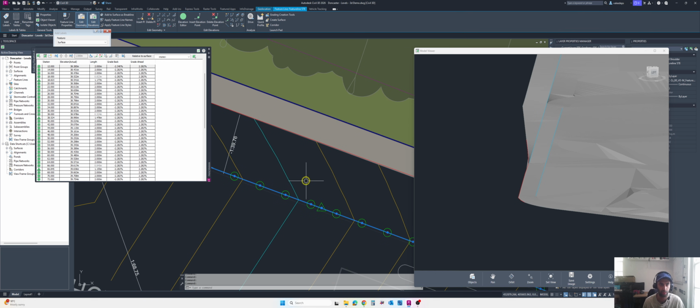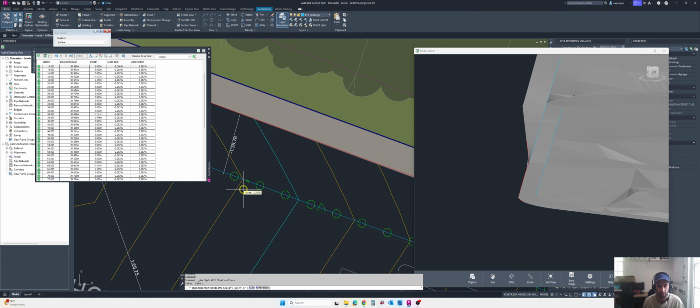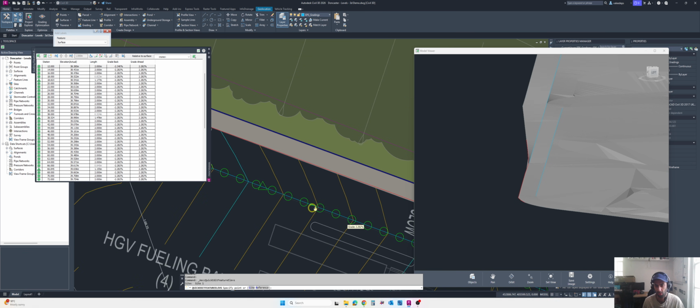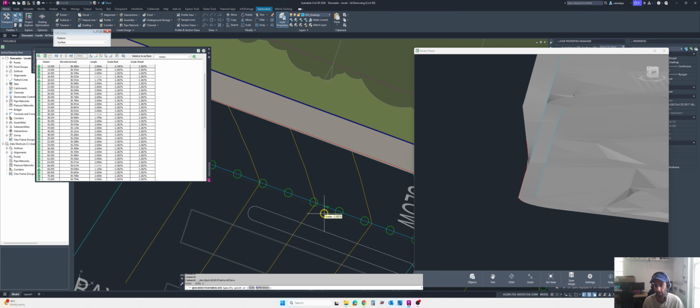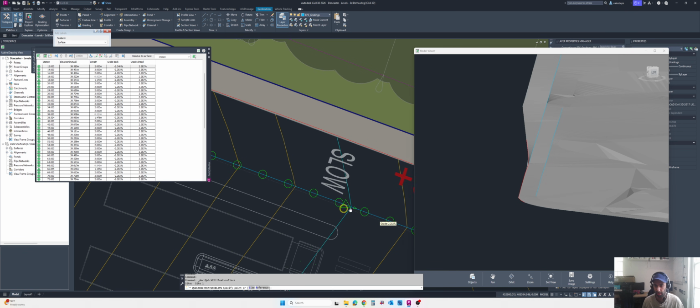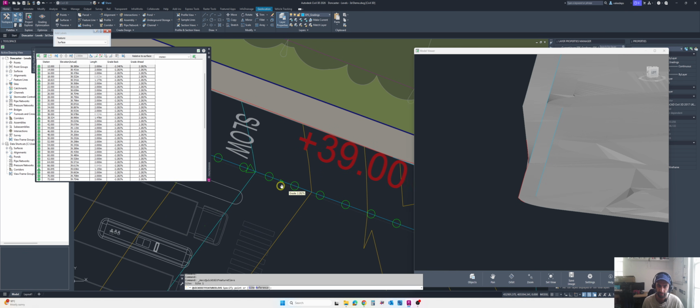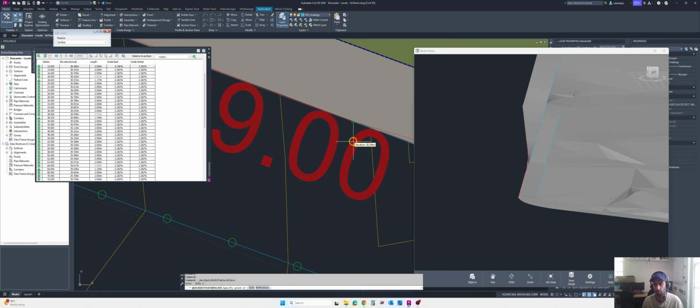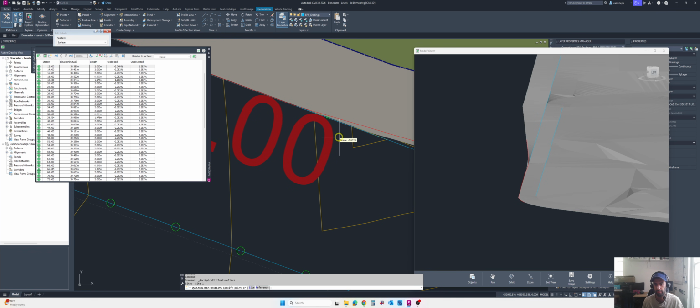to see. And also we can use the quick elevation editor. So this one, quick elevation edit, we can see the slope is 2.28, 2.28. So we can't go like 2%, 3% for this slope. Longitudinal slope is fine. Even you can go up like 4, 5%. Depends on the topography of your site. And yeah, this one is gradual slope, and on the other side that is also, I would say, the gradual. Okay, so this is a drop of 8%.